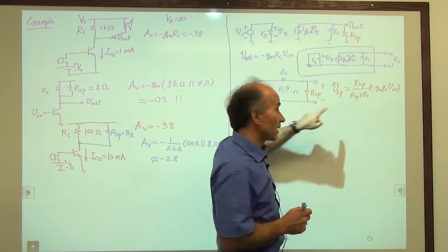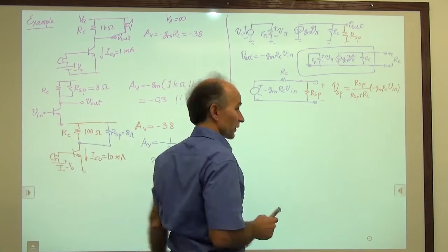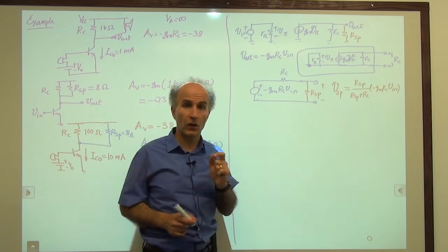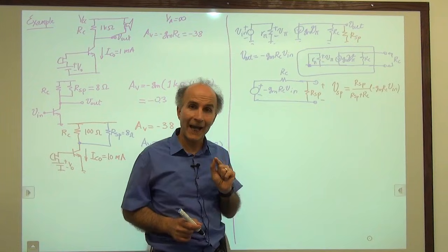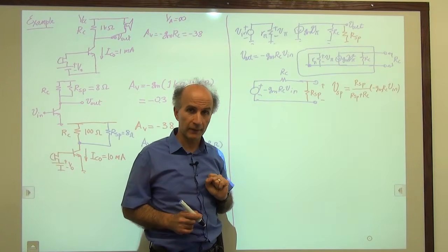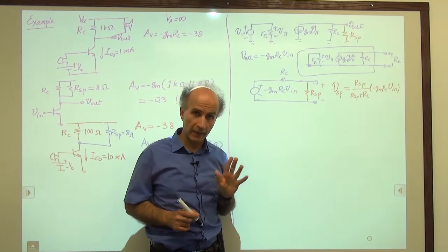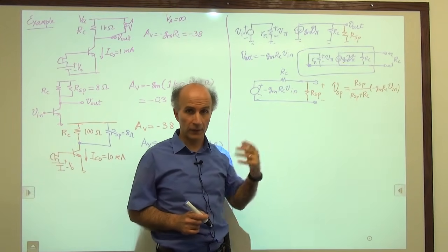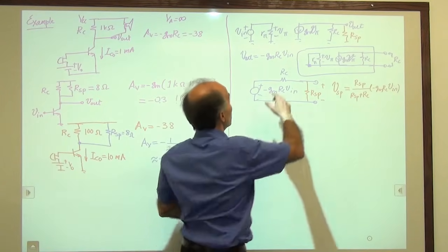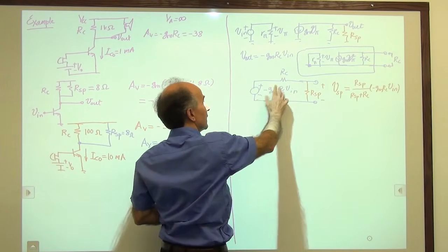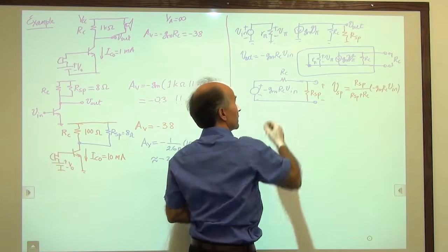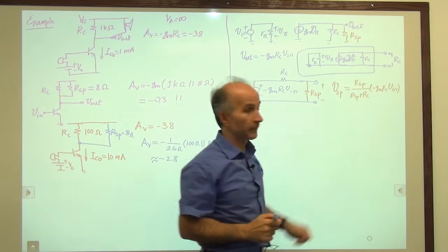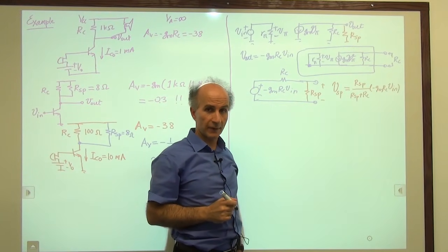That is the difference between this scenario and this scenario, right? It's just that this RC has changed. And RC is what we call the output impedance of the circuit. The best way to visualize the output impedance is just to think of the Thevenin equivalent of the circuit. We can see that when we model this by Thevenin equivalent, it is this RC, the Thevenin resistance, that creates this attenuation here. And that's what we call the output resistance.